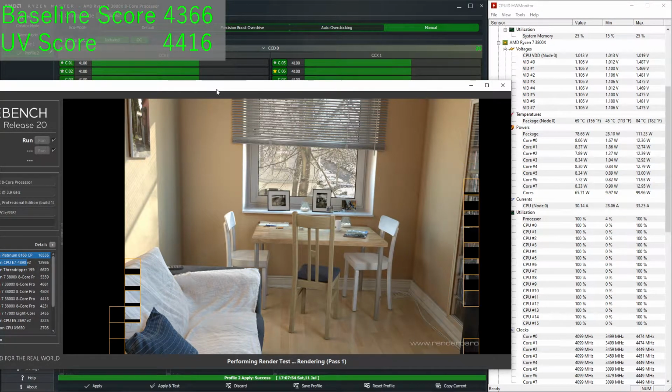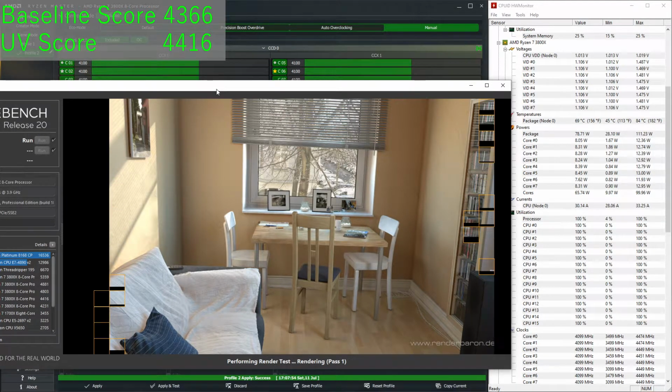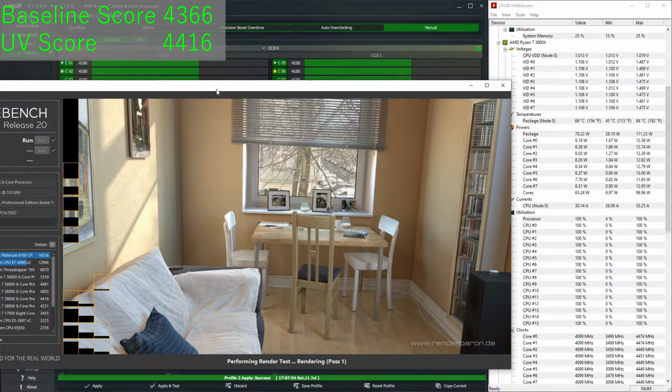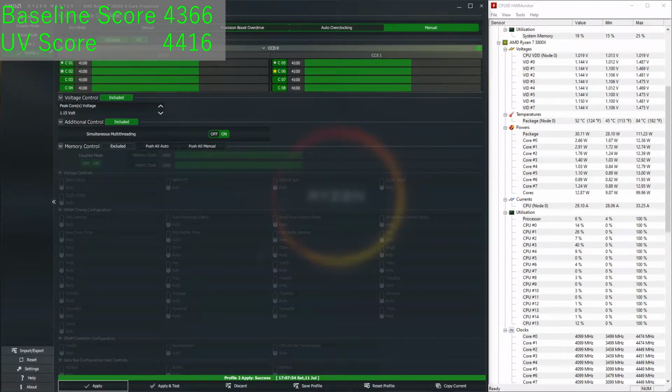At this point you probably have asked yourself, how can we lose performance at the set frequency that doesn't change? Well, at some point, while the system may not crash on you, you may see a regression in your Cinebench score. That happens when your system is at the brink of stability and the CPU is struggling to keep going. When you hit this point, you can choose one of two things. You either increase your voltage by 0.025 volts if your temperature allows it, and furthermore may even consider an attempt at overclocking. Or you didn't achieve your thermal goal, in which case you decrease frequency and try again for stability.